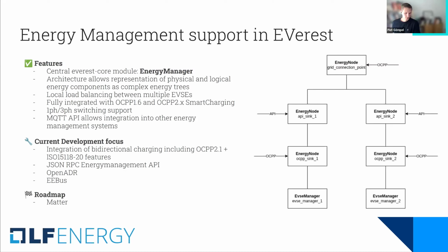What we plan to do with respect to load balancing is to actually track also the consumption of every single EVSE in order to distribute the available energy more efficiently. So let's say we split 11 kilowatts between the 2 EVSEs. In the example that I talked about, if there's just a single EVSE that only consumes 6 kilowatts, we have 5 additional kilowatts available that we can then distribute to other charging points. So this is something that we want to extend and that we will start working on soon. I hope this answers the question.